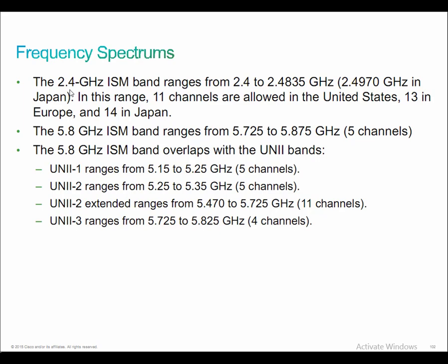You're not going to need to know specifically what these frequencies are on the test, but I do want to point out which ones are used for which specific purpose, right? The 5.15 to 5.25 gigahertz range, that's mainly indoor in the USA. For ETSI, which is the European equivalent to FCC, which is called Band A, is indoor use as well. 5.25 to 5.35, indoor/outdoor in the USA. For ETSI, it's more indoor as well, kind of defined as Band A as well.